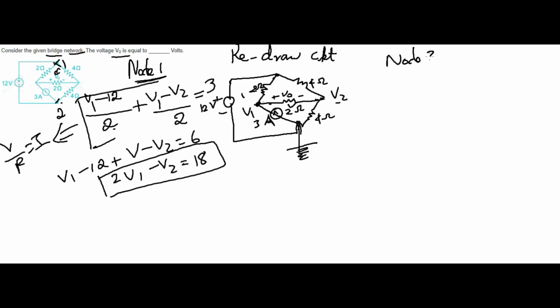And now we go for this node 2. Node 2 is another simple one. In this one I have to consider V2 first, and you have to eliminate the remaining voltages. Okay, V2, then this voltage I am taking first. So V2 minus 12 divided by what's the in between resistor? Because if I make a small way here, 4 ohm is there. So right, in between V2 and 12 only 4 ohm is there. So 4. Okay, then afterwards plus V2 in this way. Look at here, in this way, listen to me, the voltage is equal to 0 because it is going to ground. Is it right?